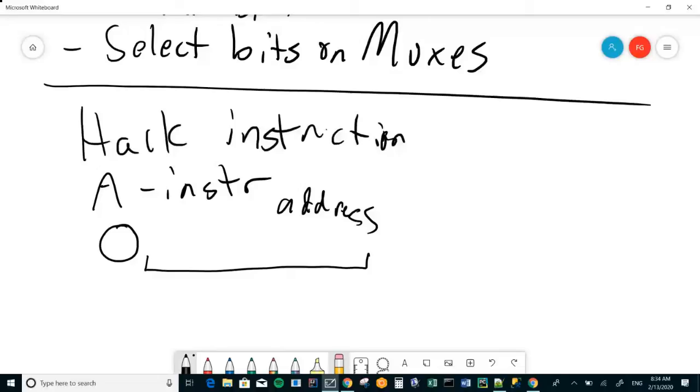we're going to have some kind of an OR between this bit and the C instruction bit saying, we're actually going to change the A register. But then when we get to that point, that's going to have to influence the select bit on the multiplexer as well. So yeah, there's some complexity involved, more than we looked at on Tuesday.